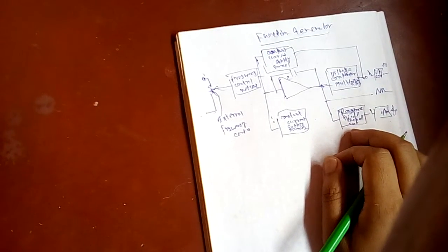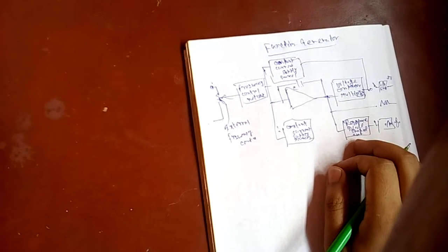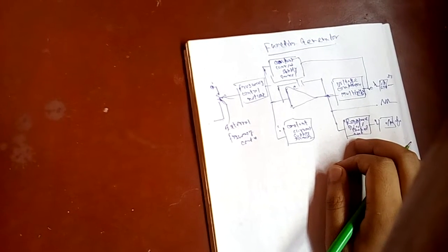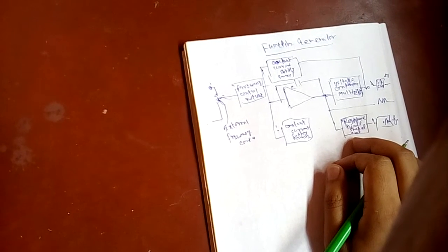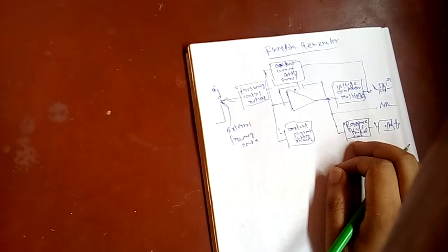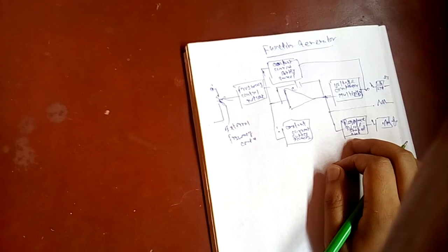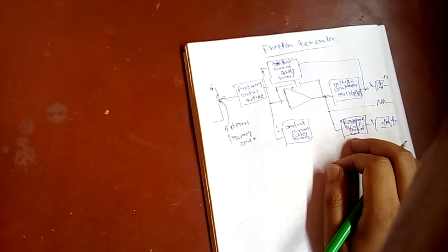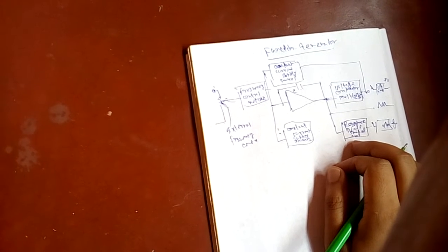So what is the important feature of the function generator? It is the capability of phase locking to an external signal source. One function generator may be used to phase lock to a second function generator, and the output signal can be displaced in phase by an adjustable amount. In addition, a function generator can phase lock to the harmonic sine wave of another function generator. By adjustment of the phase and the amplitude of the harmonics, almost any waveform may be produced by the summation of the fundamental frequency generated by the function generator and the harmonic generated by the other function generator.